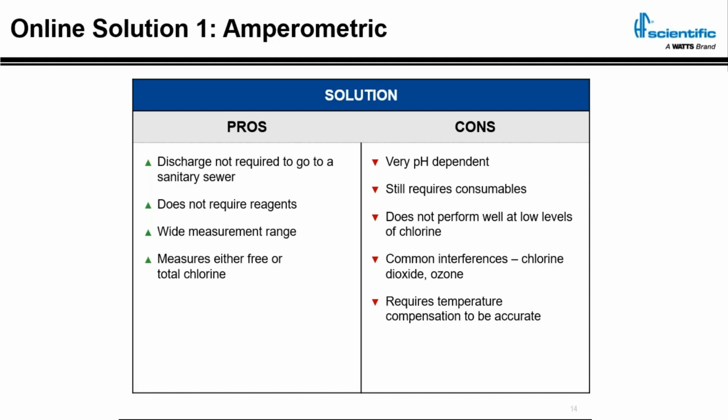The second way I see error is the pH probe must be very accurate for a correct chlorine measurement, and it's very hard to measure pH in a clean sample. I consider surface water a clean sample. Low conductivity samples, it's tough to measure pH in.